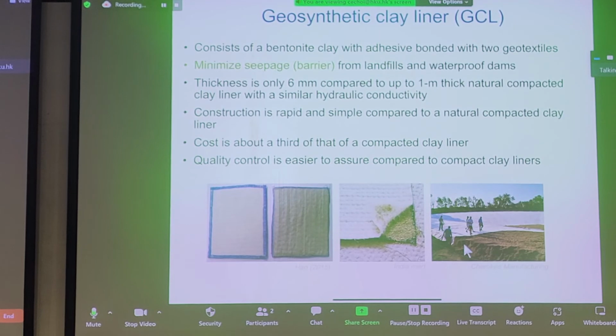We also have a GCL, what you saw on the table earlier. We call this a geosynthetic clay liner. Clay we know is very impervious. So what's interesting about this is if you open up one of these, you see clay inside. Here's an example. You have fabric that's closed off. Inside and between there's a thin layer of clay. And we know that clay is very impervious. If you wet the clay, you can get a very nice barrier system as well. So GCLs are often used to prevent infiltration, leachate, also used for barriers for landfills and dams.